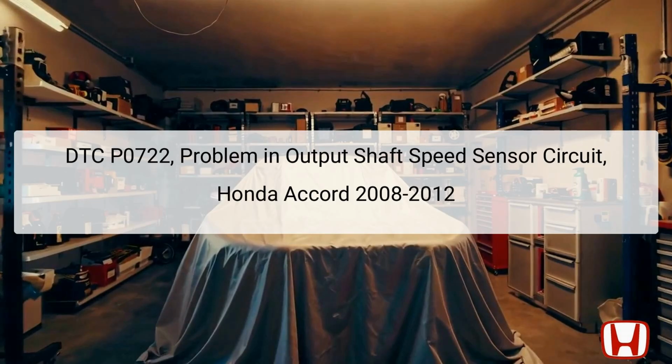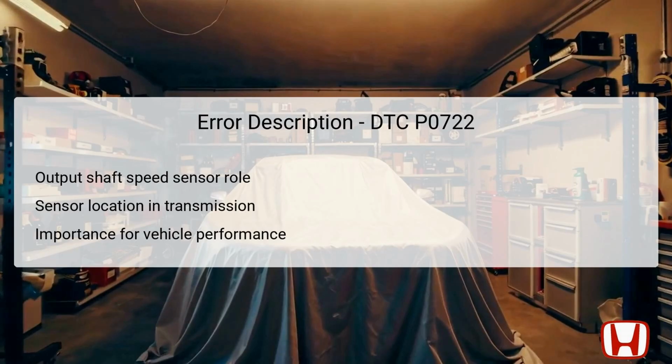Typically, this code surfaces when there is an electrical failure in the circuit rather than a mechanical issue within the transmission. Before proceeding with troubleshooting, it is essential to document all freeze frame data and snapshot information using the Honda Diagnostic System, HDS. The output shaft speed sensor measures the rotation speed of the output shaft, which is crucial for the transmission control module, TCM, to optimize shift points.